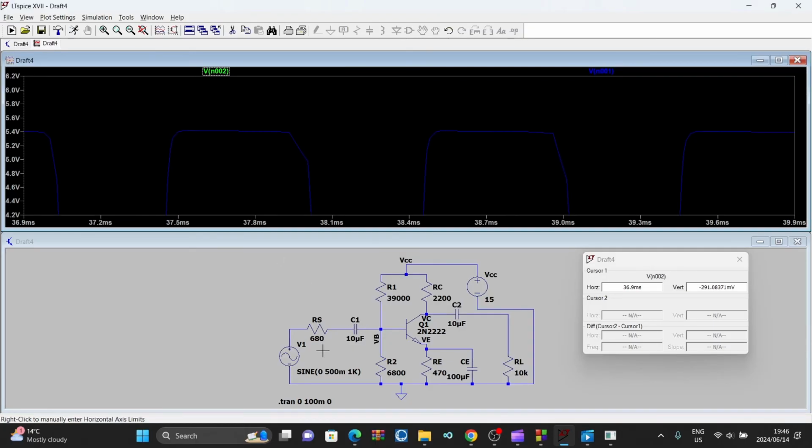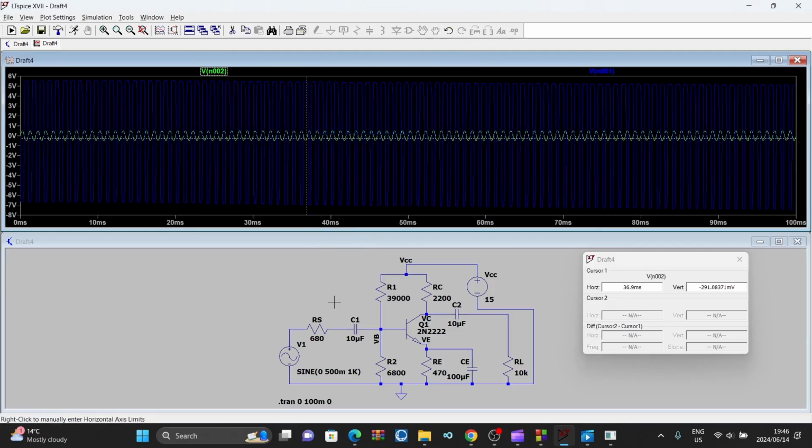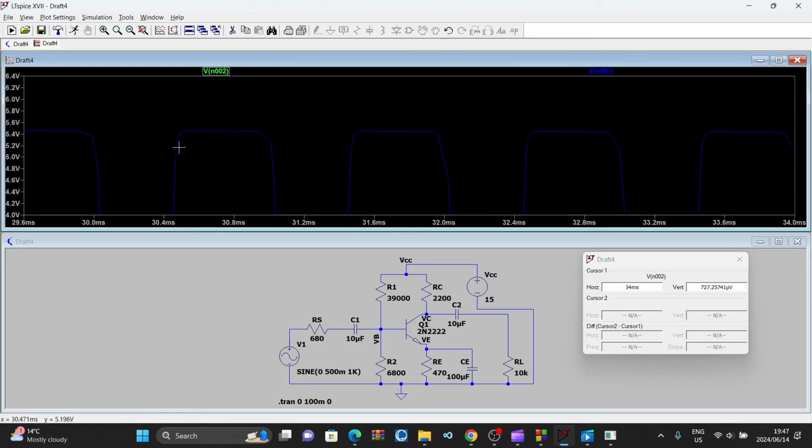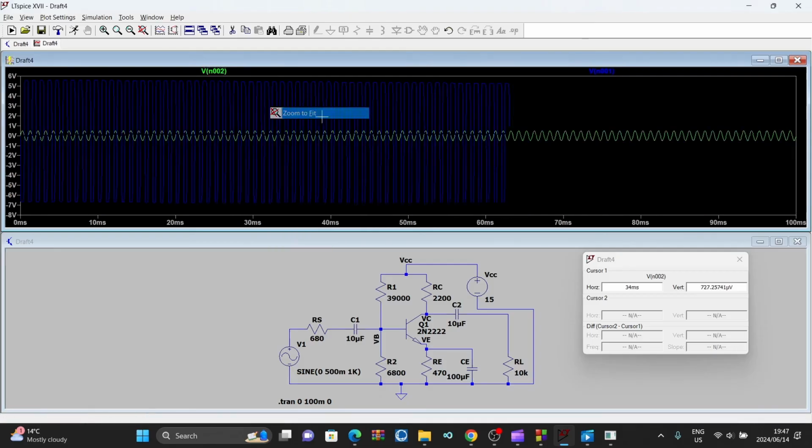So you have to look for the exact value at which it starts getting flatter, and which peak. In this case, I think my positive peak is starting to distort, because it's a bigger difference compared to my negative peak. So for me it's the positive peak which is getting distorted, because it's getting flatter. It has more flat.